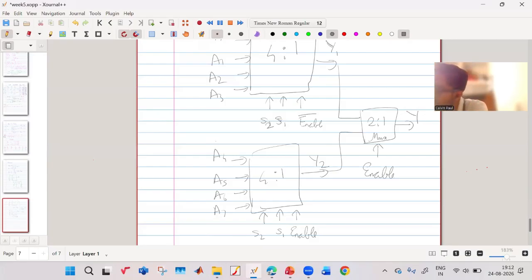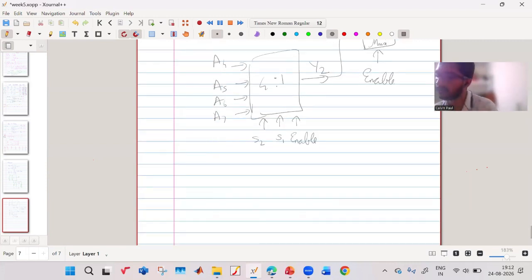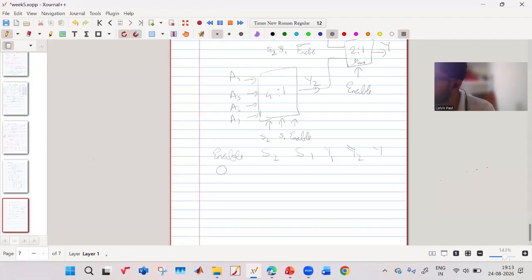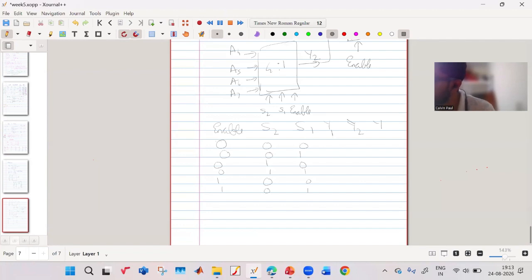So you have enable, S2, S1, Y1, Y2, and Y. This is 0, this is 0, 0, 0, 0, 1, 0, 1, 0, 0, 1, 1, 1, 0, 0, 1, 0, 1, 1, 1, 0, 1, 1, 1.